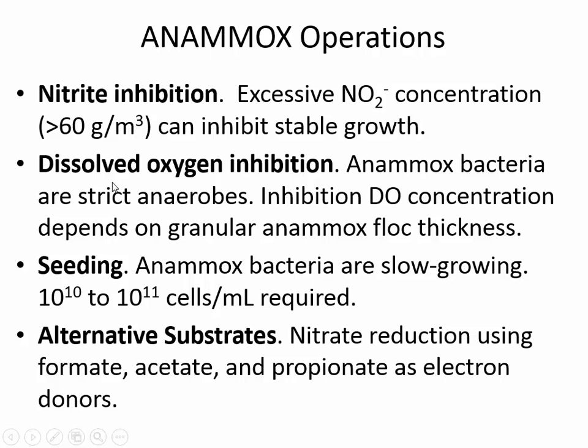As I already mentioned, this is not a quick process to kickstart, and they've seen that you don't see removal of ammonia until about 10 to the 10th cells per milliliter are present in the reactor. So the concentrations that are required are quite high, and they'll seed the process to begin with just to prevent a startup of several weeks.